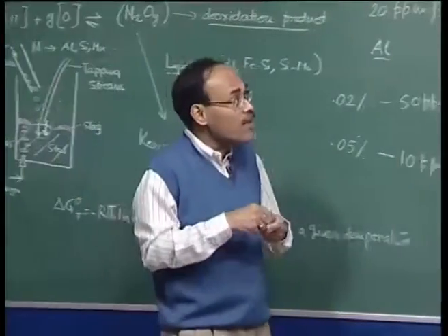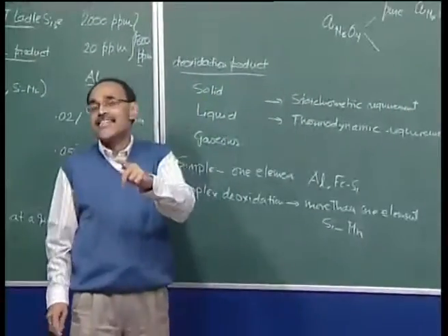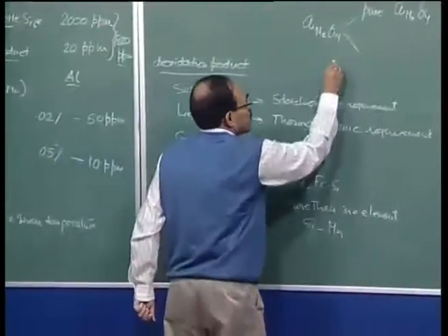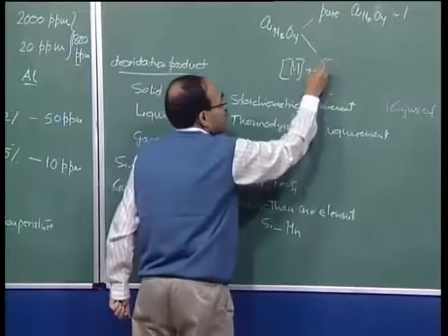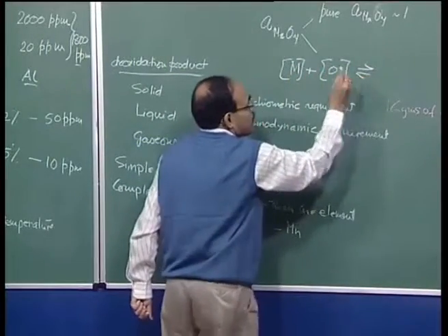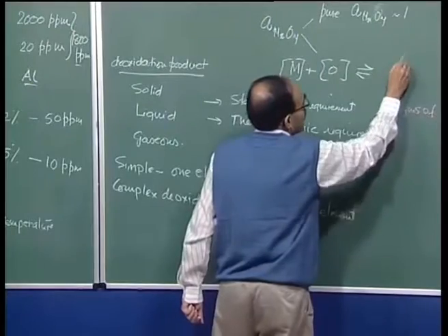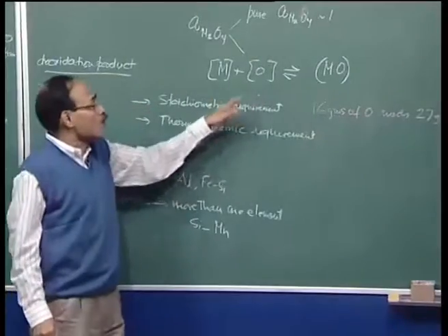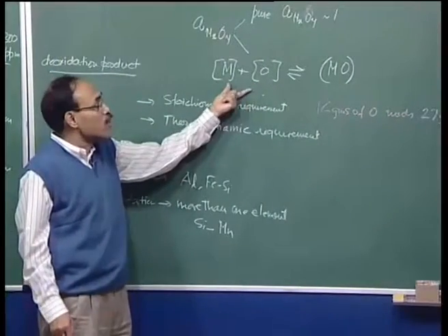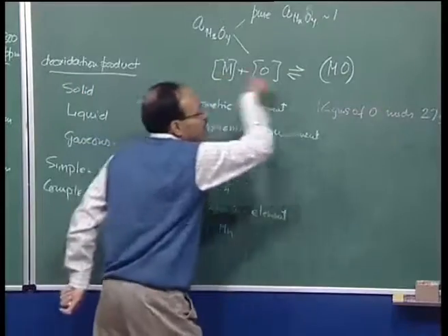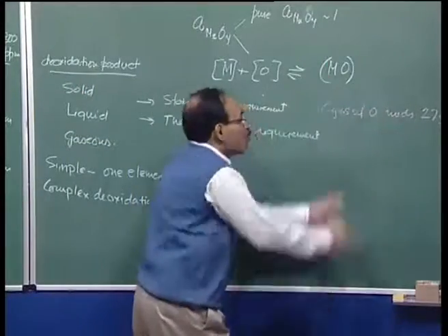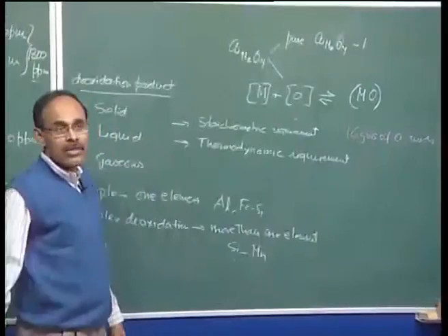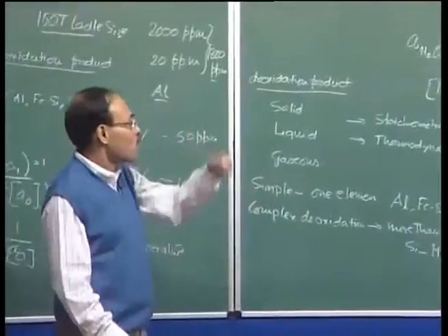So, therefore, the activity of silica is going to be substantially less in the presence of a calcium silicate slag, and in that case, if we look at the deoxidation reaction, I am writing it in simple form, MO, we can say that the lesser the activity of MO, the more the efficiency of the deoxidation reaction. Lesser activity means as if we are continuously removing the product from the site, and as a result the reaction will proceed more spontaneously towards the forward direction itself.